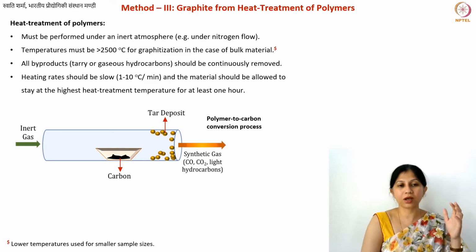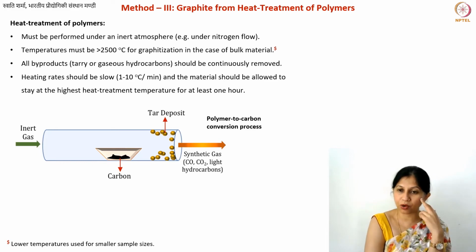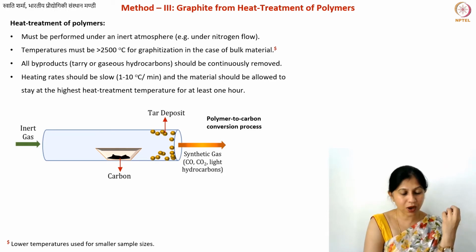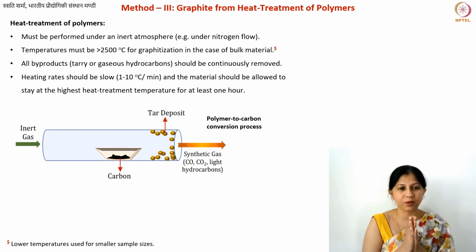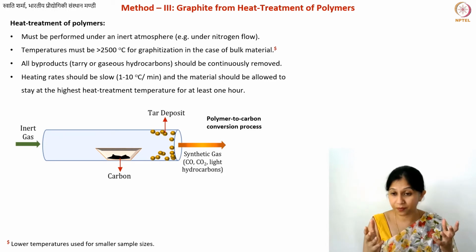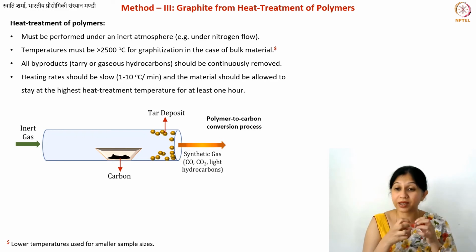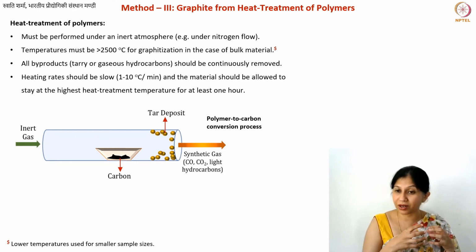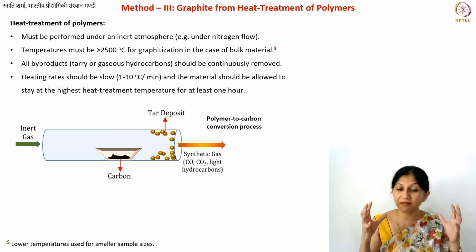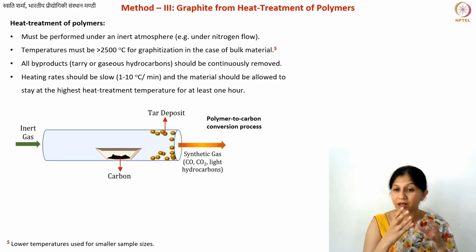So at some point we'll also learn that this entire process is a combination of both thermodynamics and kinetics. Thermodynamics in the sense that you have various reactions. Every reaction has a different energy. Why I'm saying various reactions: when your polymers are broken into smaller hydrocarbons, each hydrocarbon also might be breaking into further smaller hydrocarbons. Or there is also this one reaction going on where you have carbon radicals which are attaching with each other and forming a solid carbon material. So it's a very, very complex mixture at any given temperature point.